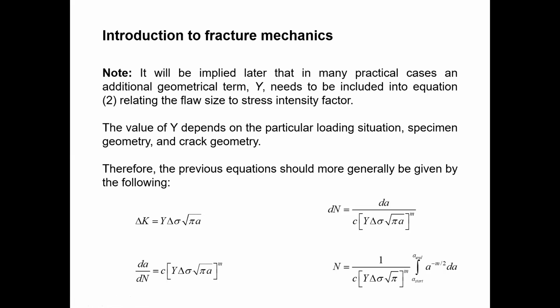If the specimen has a large width with a small crack length, it has a different effect than a small width with the same size of crack. A larger width has a small effect, but the effect is large for a small width. So Y depends on the crack geometry, the specimen geometry, and the loading type and situation. You can see these three categories.